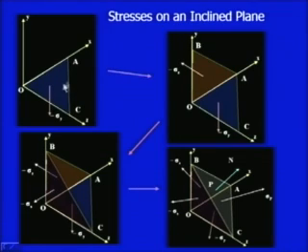If we start from the first slide, we can see we have the xz plane where this compressive normal stress is there along the lower direction. So that's why it is termed as minus sigma y. If we are taking the other plane, which is the xy plane, we have the sigma z. Since it is compressive, as I told you, if it is a compressive stress then it is termed as negative. So this is minus sigma z and this is minus sigma y. And if we go to the other slots of these stress components, we can find we have all these sigma x, sigma z, sigma y as the normal stress components.